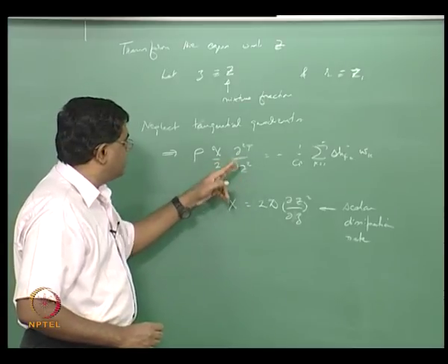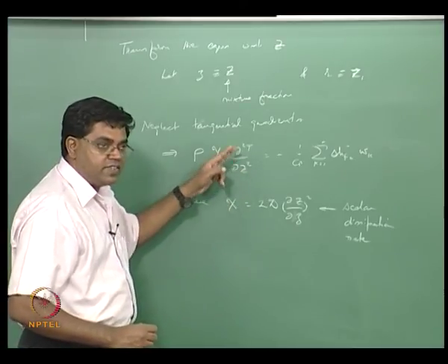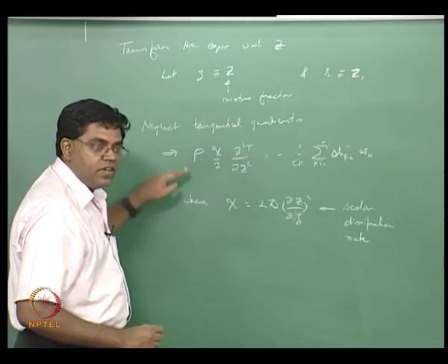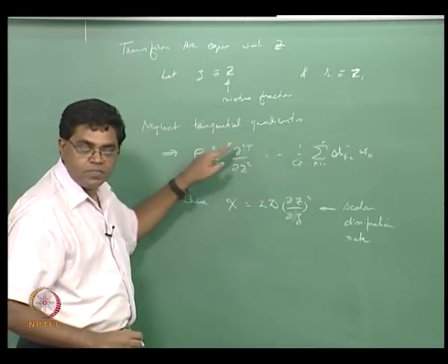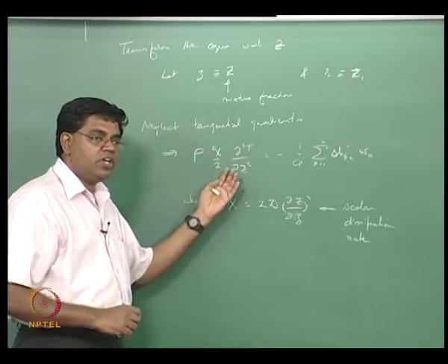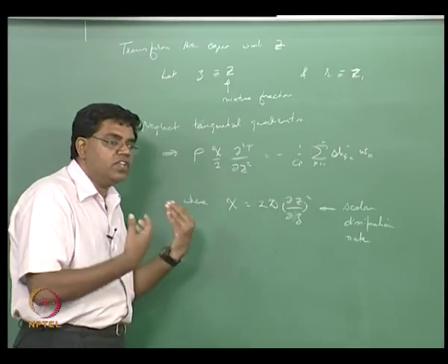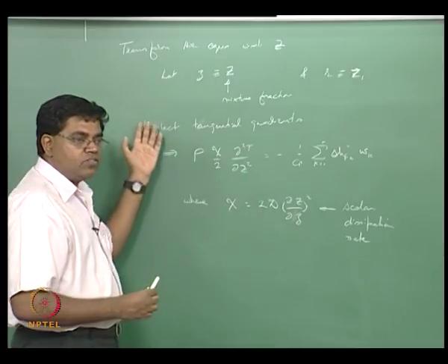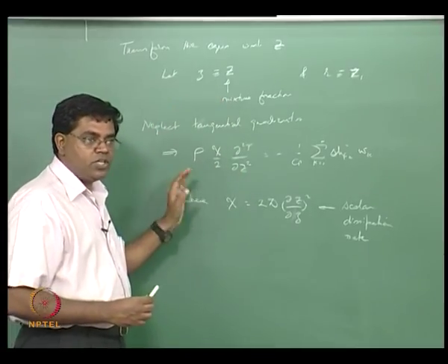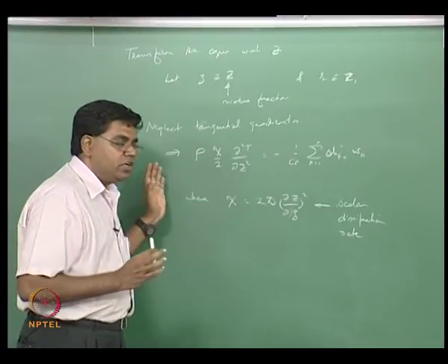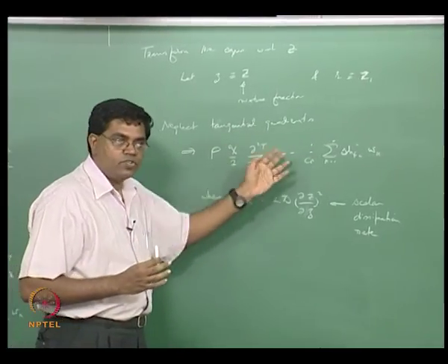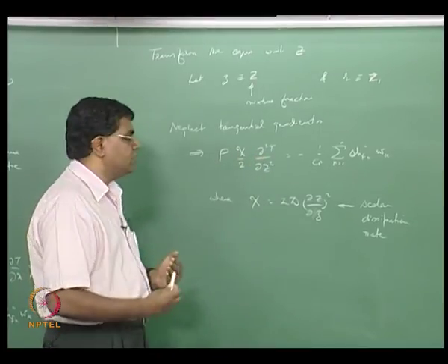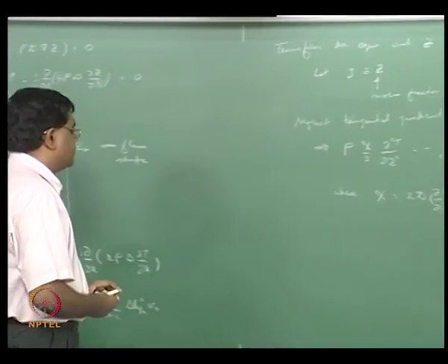You have it as a second derivative in capital Z, which is the mixture fraction. So this is a derivative in the mixture fraction space, so it is a transformation that contains within it convection as well as diffusion. But by making this transformation in terms of the mixture fraction, we have essentially enabled it to look like a reactive diffusive balance, alright, but the transformation contains in it the convective and the diffusive effects.